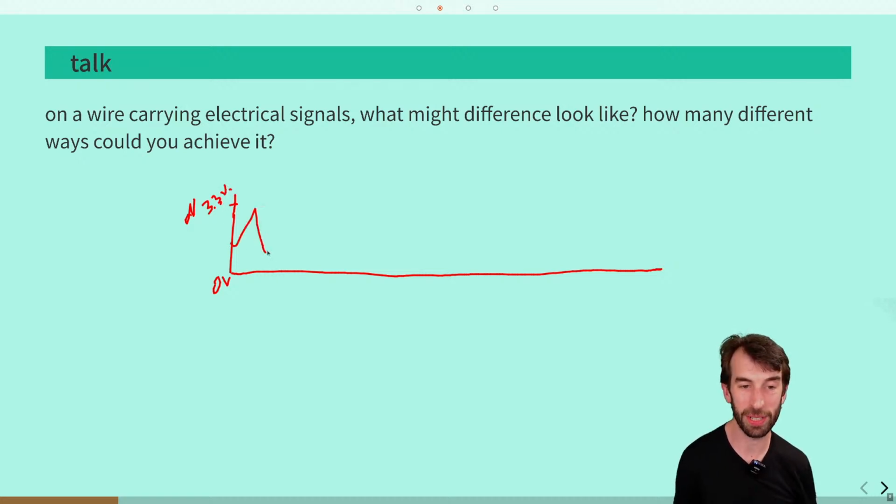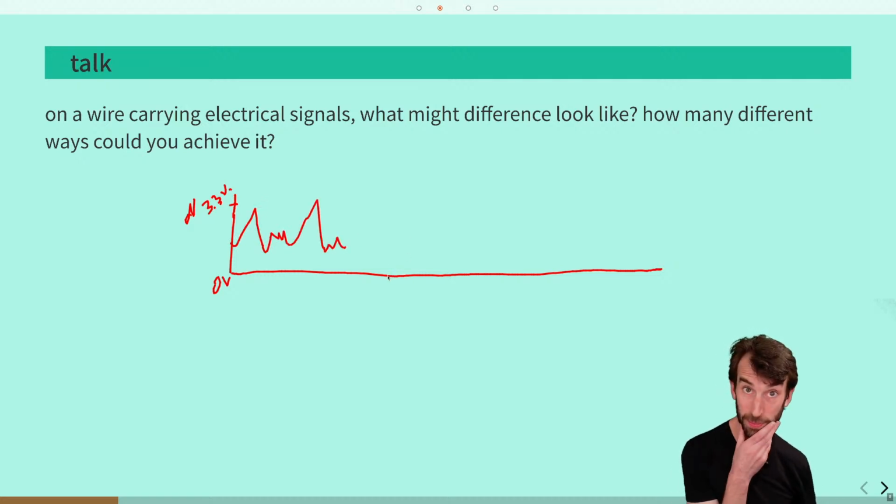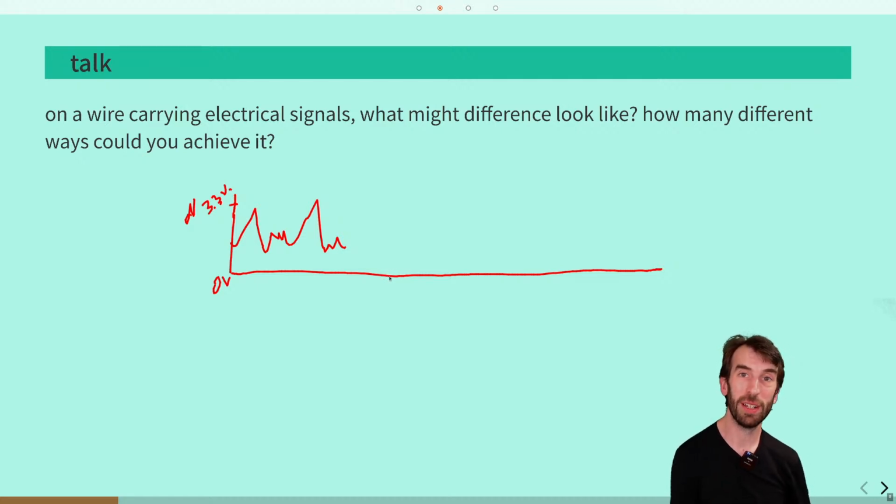And so electrical signals can have changing voltages, and you know from working with assignment 1 with GPIO that you can change the voltage on a GPIO pin from being low, which would be in this graph equivalent to 0 volts, to high, which in this graph would be 3.3 volts, because I've chosen 3.3 not for no reason, but because that's the power level that the microbit operates at.